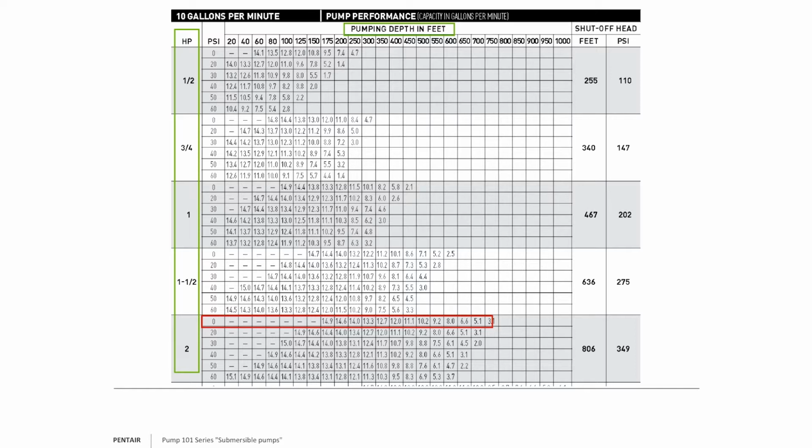It's because, what's the definition of total dynamic head? Friction loss, service pressure, elevation, and drawdown. Right? Service pressure is included. So, I would look at 0 PSI because I've already calculated it, but I would look at depth of water as being 500 feet. And if you look at 500 feet, 0 PSI, 10.2 gallons per minute. So I'm feeling pretty good about that number, all right?